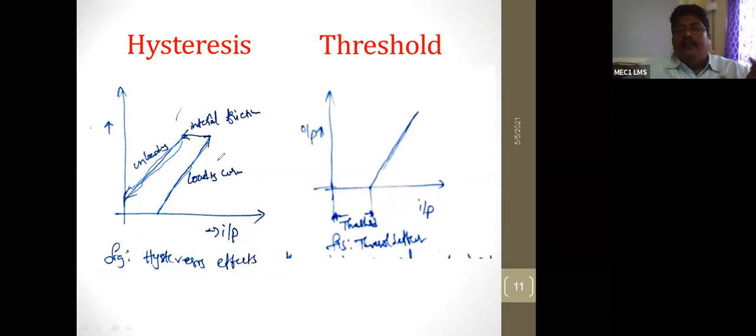Here I added weight to determine the performance of an engine. 1 kg, 2 kg, 3 kg, 4 kg, 5 kg, like that. I increased. So that means that is the input. The load is increased. Obviously, you know very known. When the load is increased, automatically the speed of the engine, what happens? Speed of the engine decreases.